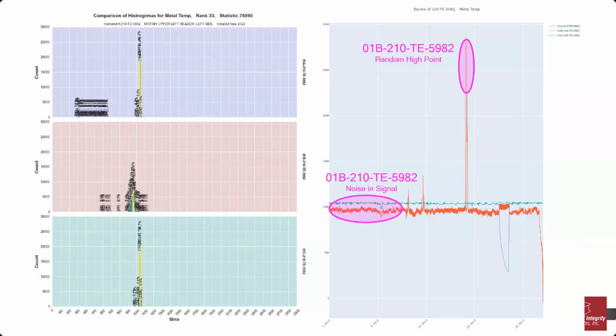If you're a more base load operation, creep may be more of a concern long term because you're going to be at higher pressures and higher temperatures for a longer amount of time. Whereas a cycling plant is going to be more fatigue related, because you're going to have large temperature differentials during your startups and shutdowns. For the most part, all the equipment you would monitor would be about the same, because you want to account for both peaking and baseload operation. Anything to add to that, Kane?